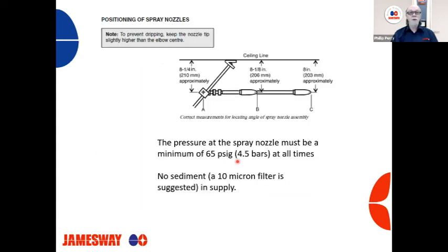Here's the positioning of our spray nozzles. Our short nozzle is 8 inches and an eighth, and then it's 6 millimeters. And then our long nozzle is 8 inches. And then it's very important, the elbow is 8 1/4 inches. I've gone into hatcheries that had this 8 inches measured from the ceiling properly, but the elbow would be down here, so the nozzle's pointing straight up at the top of the cabinet. I've seen it at the top too, where it has moved on here.